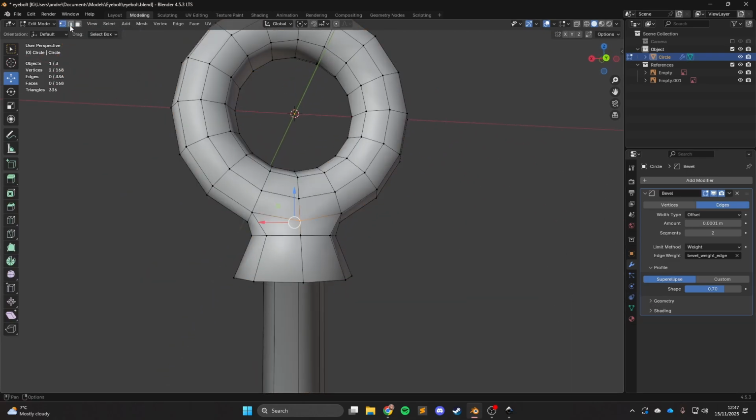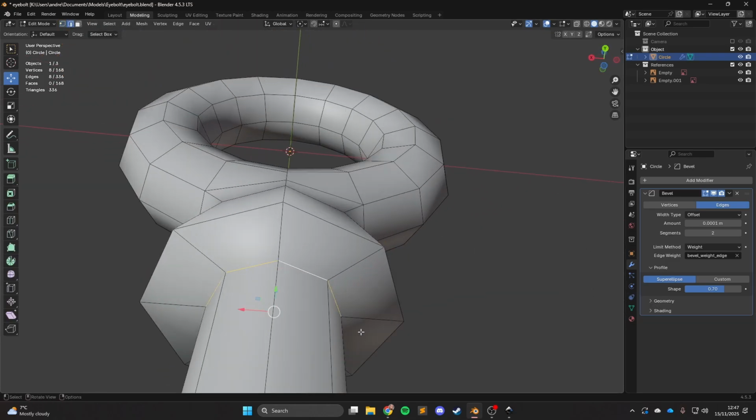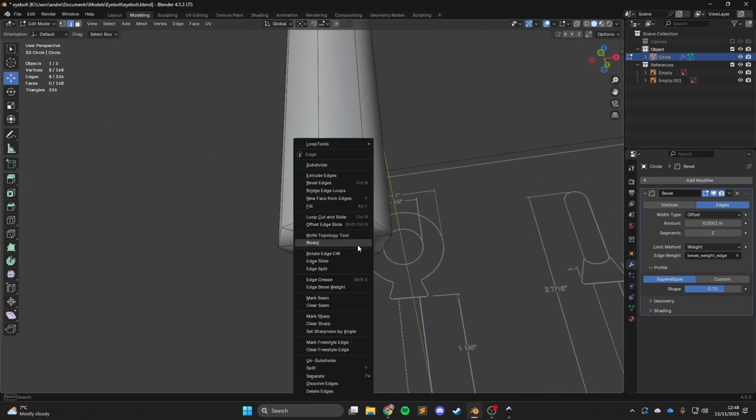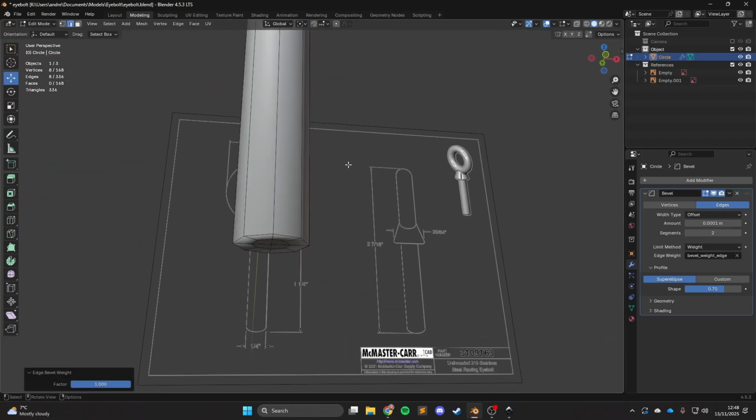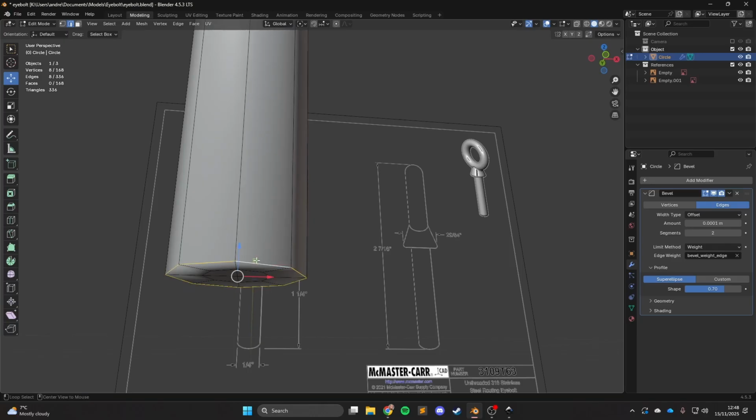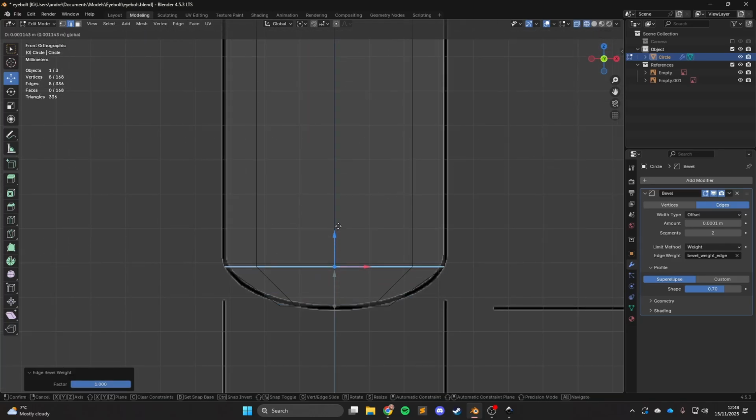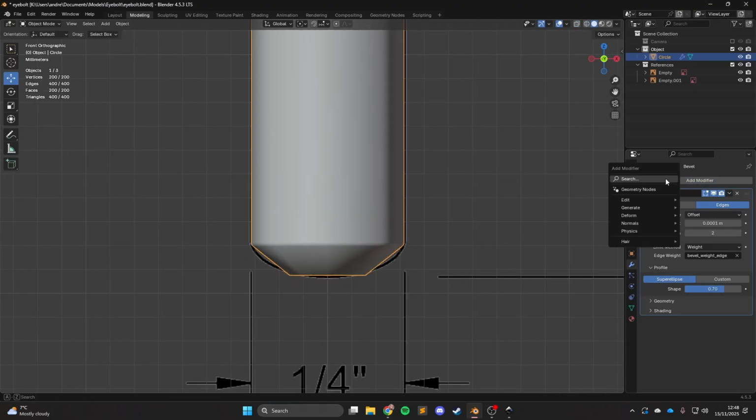And now we can select the sections that we want to have sharp edges, which is really only this one at the moment. Or rather, okay, it'll be this one as well, but we will then pull that up to about there. And now we can add our subdivision.